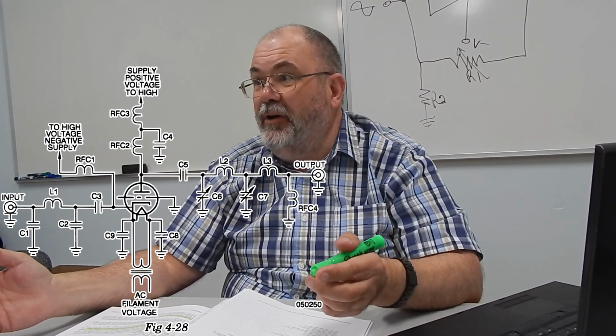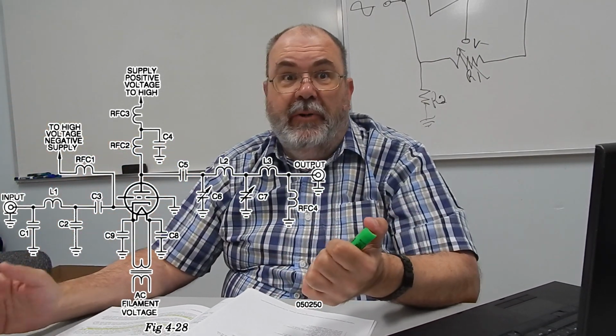So you can't just cookie cutter out an amplifier, and that's one reason that these high power RF amplifiers are expensive. It's nothing that you can just mass produce and ship out the door. You produce one, you have to have someone sit down, put it on a test bench, put spectrum analyzers on it, and sit there with capacitors soldering in by hand until it's neutralized. Then they can pack it up and ship it out. And that's an expensive process.